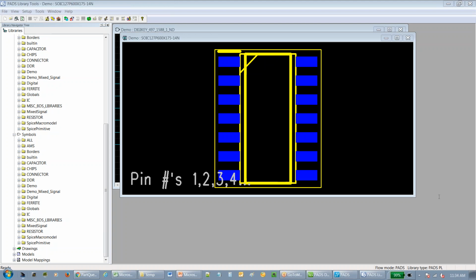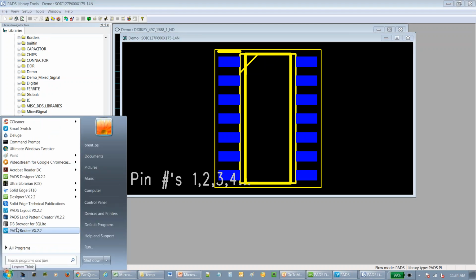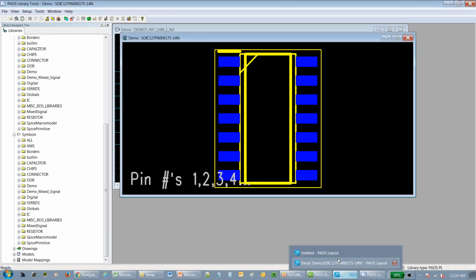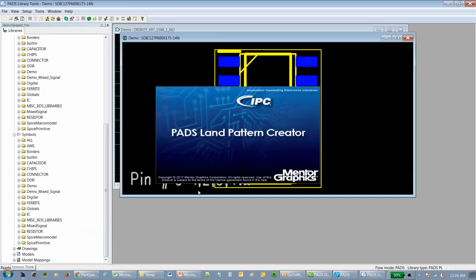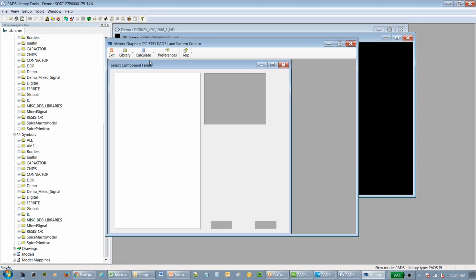Do you have an option to create rectangular pad stacks? I know IPC uses rounded edges. Just curious. I think the land pattern creator allows you to choose oblong or rectangle pins. So yes, that capability is there.